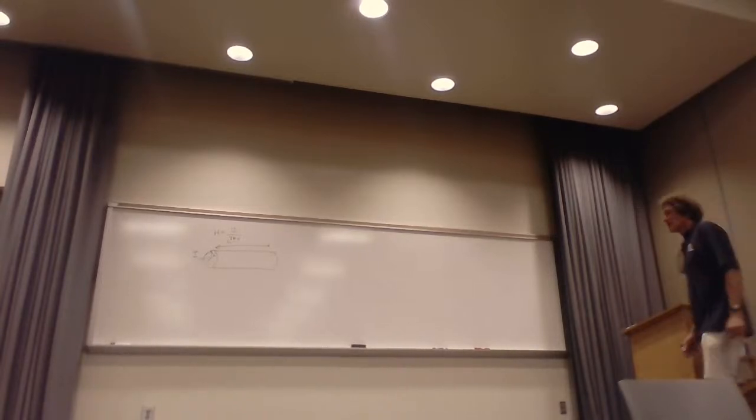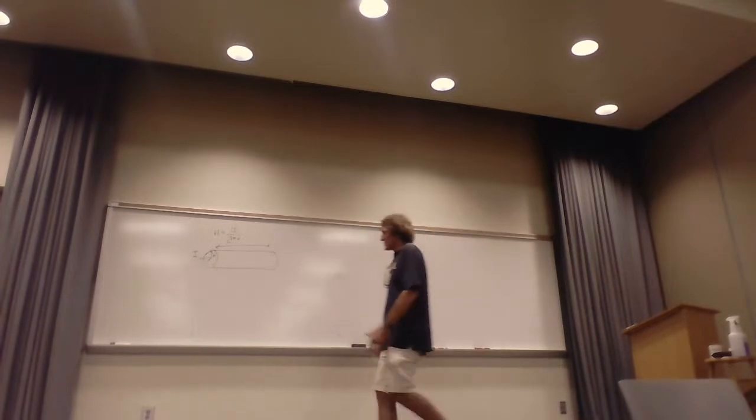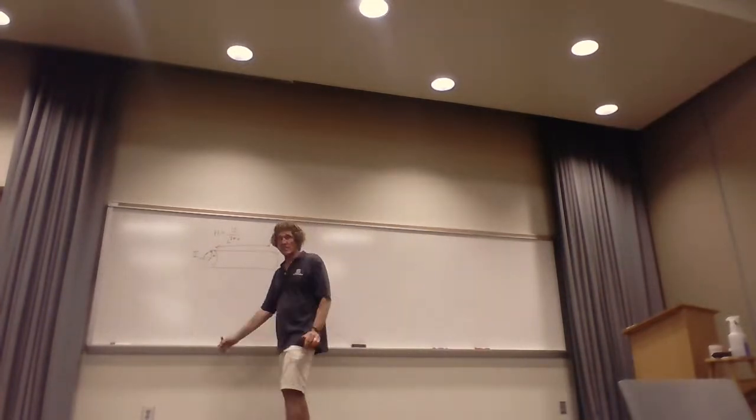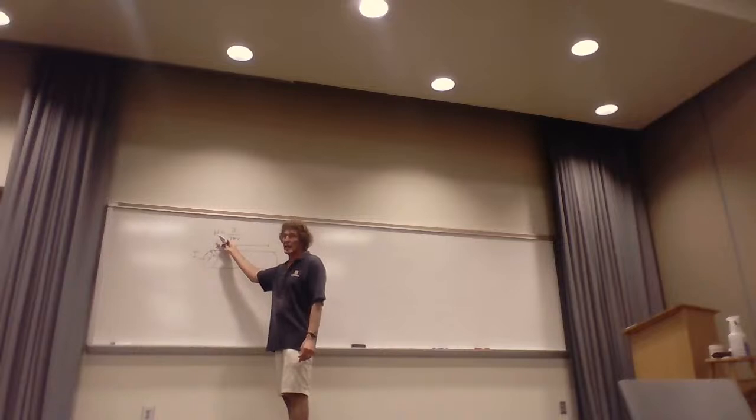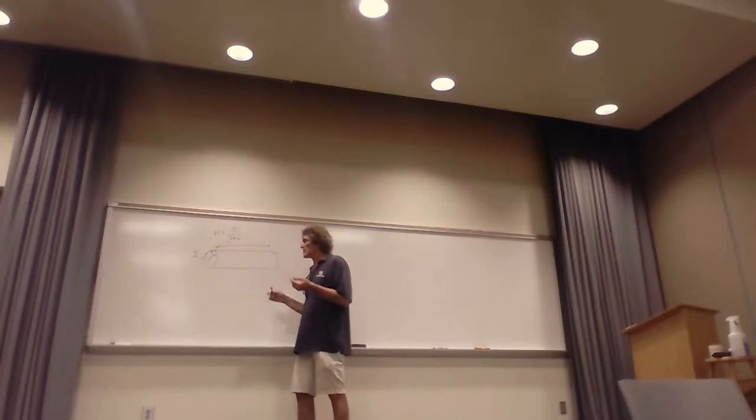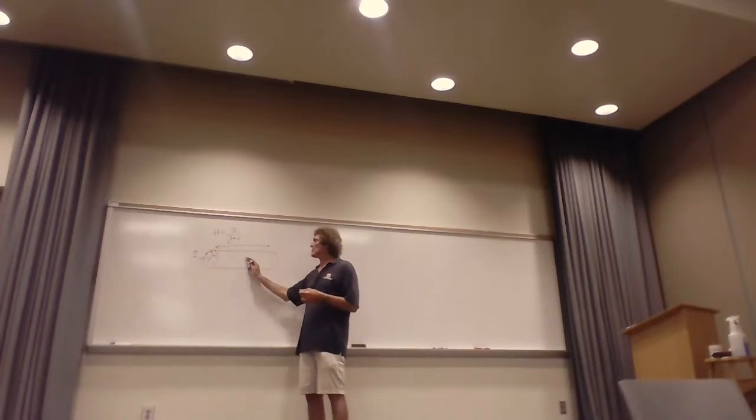So anyway, that would be the H field if this thing was infinitely long. Do y'all remember that? That's a very long wire, and you're close to it, that's the H field. The magnetic energy would be this H field squared times mu. That would be the energy density, and you could integrate that around. But internal here, the H field isn't just I over 2 pi r. It depends on how much I is inside that region, right?